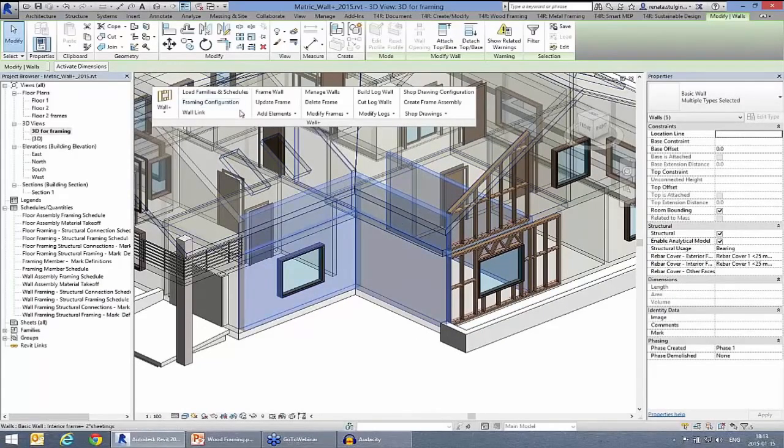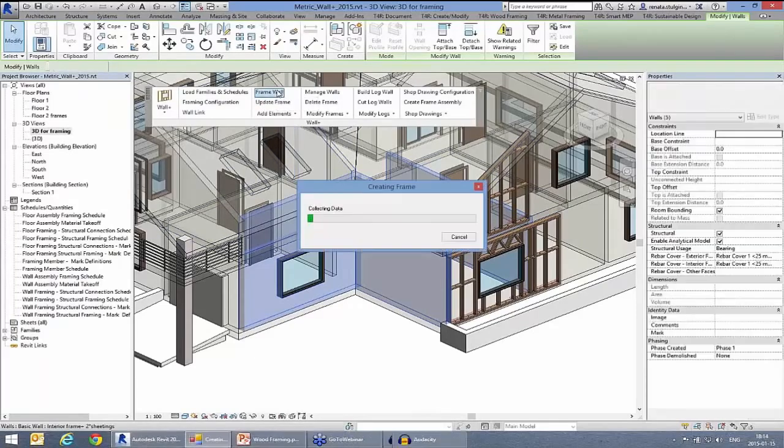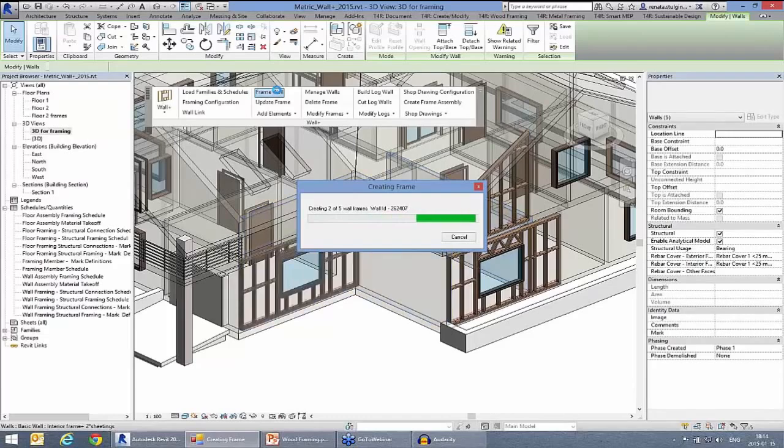So now I'm going to pick one internal wall and 4 external walls, and now let's frame those 5 walls. So now the tool will understand. Still, if I'm selecting several different types, still the tool will know what exactly to put into every layer, and how to frame that wall, and how to frame every layer. Okay. So now the tool is reading the type information, it's reading configuration settings, and it's framing our walls.